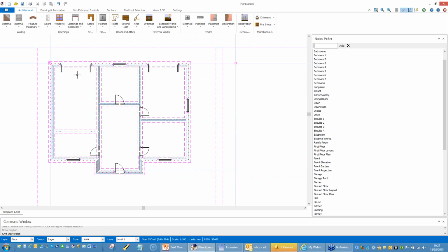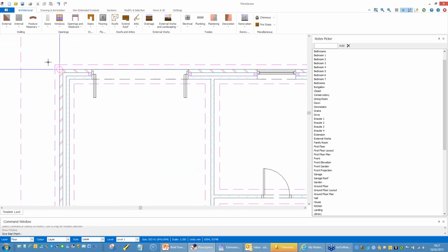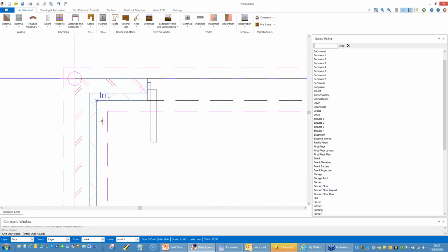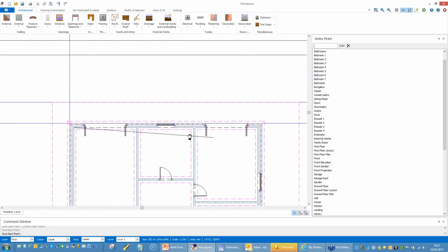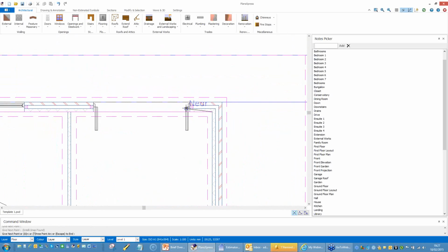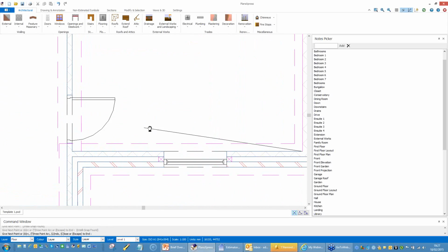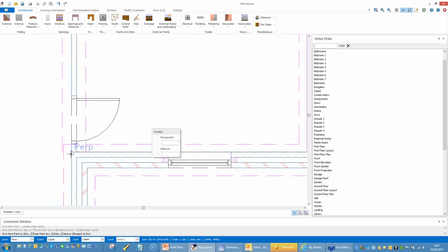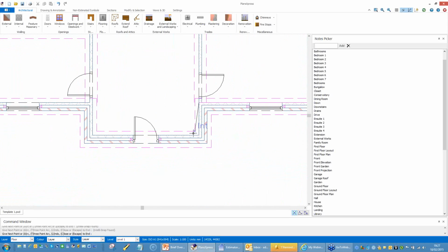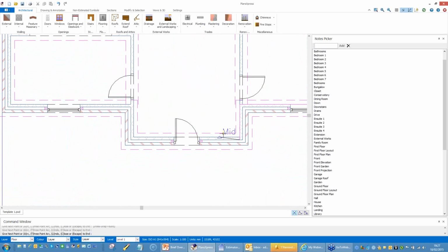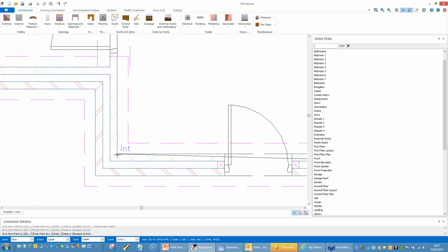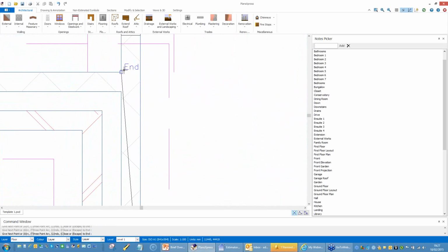Okay. Incidentally, at the bottom here, there's the command window, which is actually a sort of help window, and it's saying to me, give me the start point of the slab. Well, I'm actually going to click around the corner of this slab, and as I say, I'm going to go around the overall perimeter of it. I'm cheating a little bit because I'm whacking this slab right the way through the job for speed. I actually made a small mistake there.